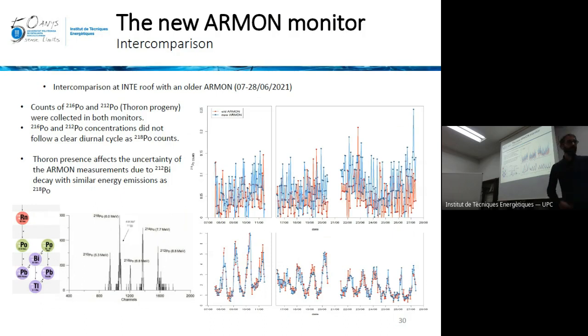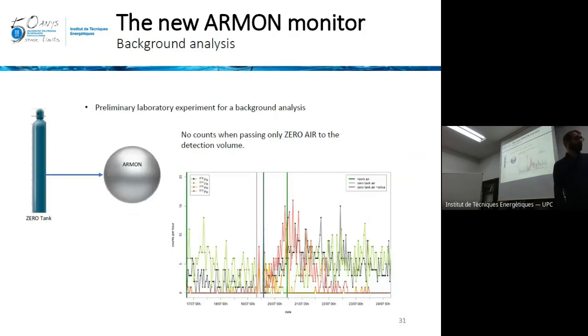So we decided to do a background check of what was happening in the instrument when zero air was coming in, and what was happening in background conditions. So we put zero air into the instrument from a tank. We could see that all counts were going to zero.